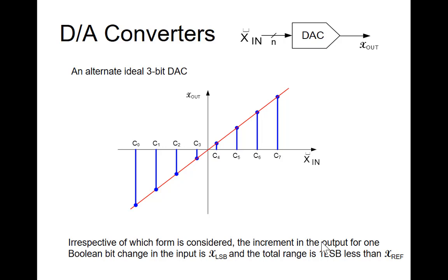Yeah, it might appear that way here, but keep in mind this is a Boolean axis. So this is not defined between these points. By definition, if you plot it this way, these will be uniformly spaced because these are just Boolean codes. There is no Boolean code between 2 of the existing Boolean codes for a given bit resolution.